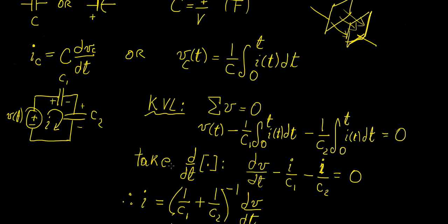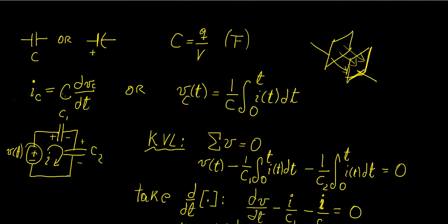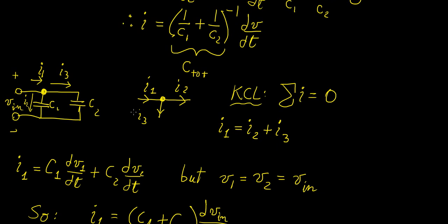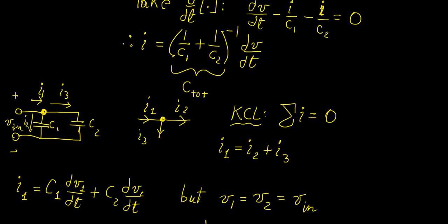Now, we're going to use the definition of the current across a capacitor, and we're going to write down the expression in those terms. So in this case, we're going to have I1 is equal to C1 times dV1 over dt, which is the potential drop across this one, plus C2 times the derivative of the potential drop across this one. But notice that these two are in parallel.